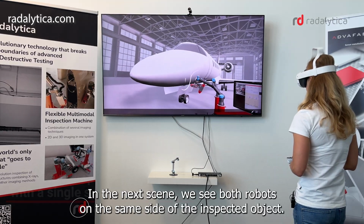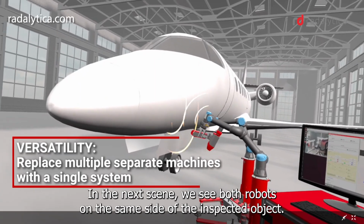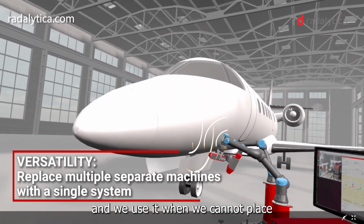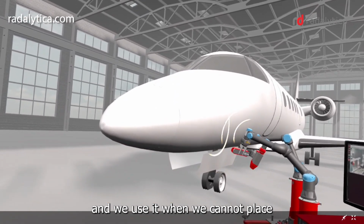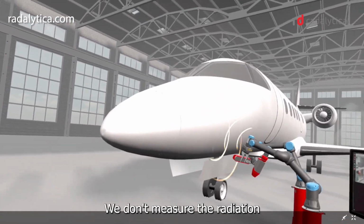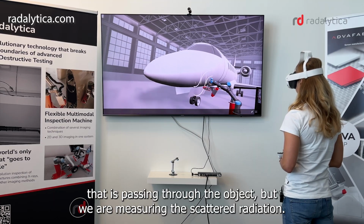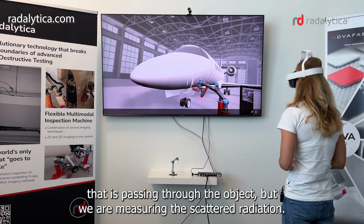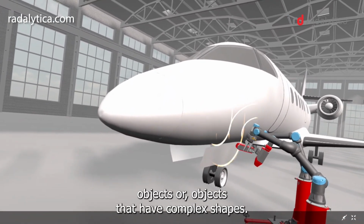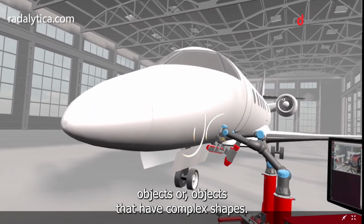In the next scene we see both robots on the same side of the inspected object. This approach is called backscattering, and we use it when we cannot place the inspected object in between both robots. We don't measure the radiation that is passing through the object, but we are measuring the scattered radiation. And with this approach we can scan very large objects or objects that have complex shapes.